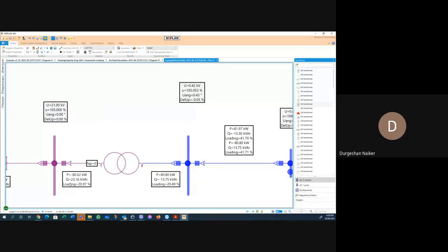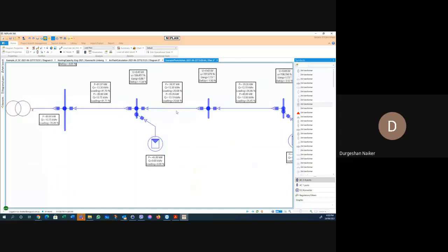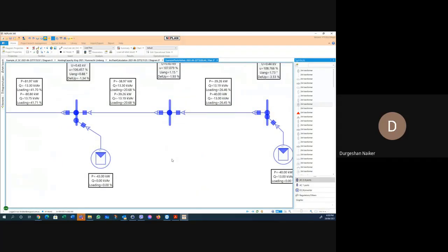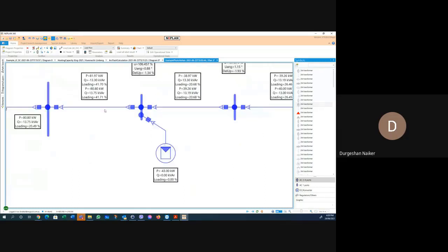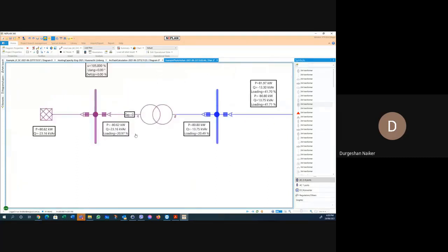What it is telling me is, if I look from this side, each of the cells is making about 20 kilowatts each. This one is doing 43, sorry. And therefore it's traveling across through the bus bar, through the cable here, and out here, then stepped up and goes through to the grid. That's what the grid is importing.